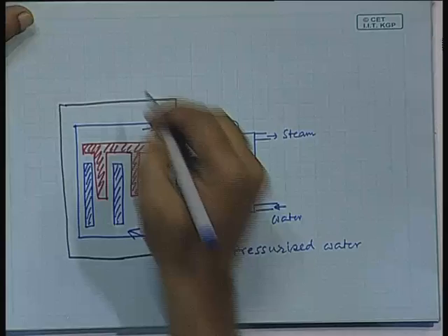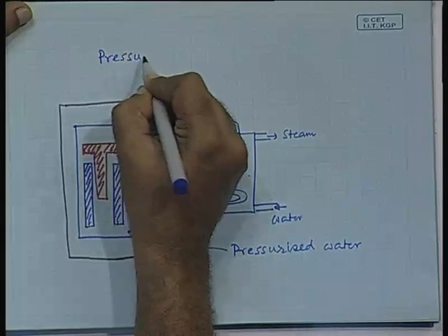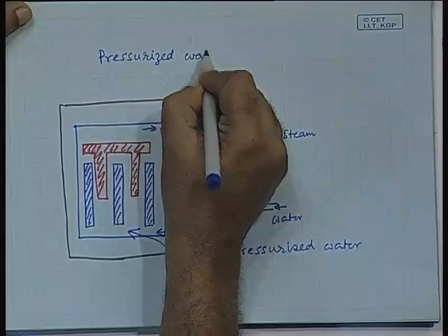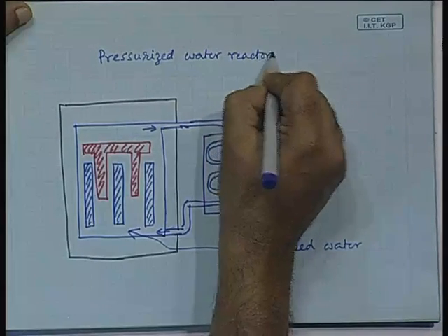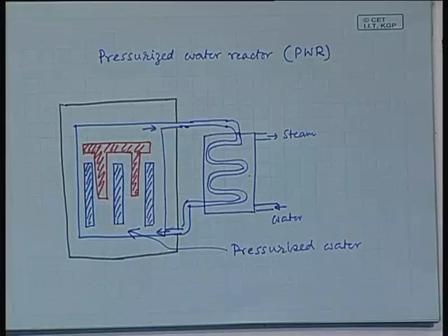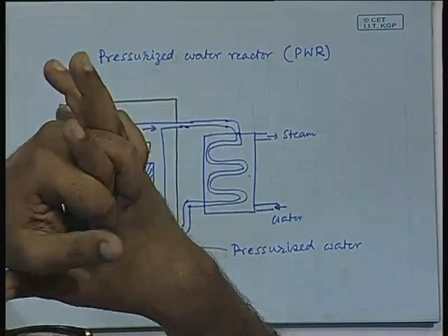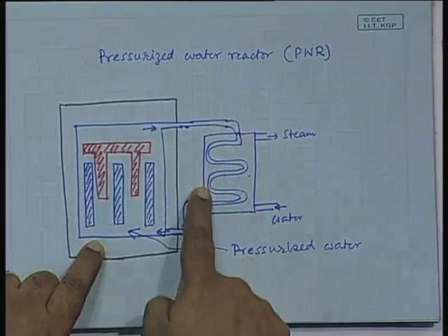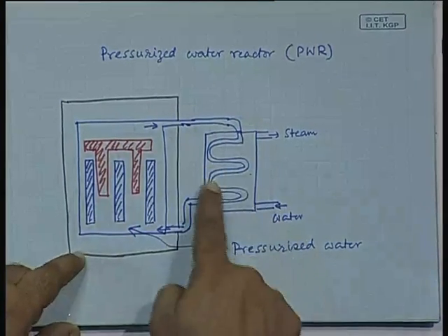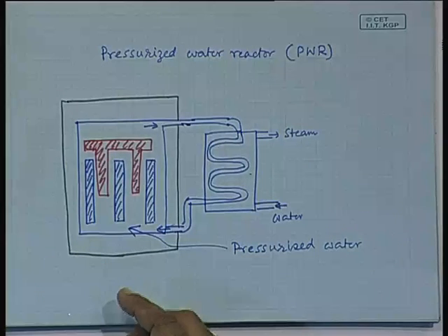So, this is called the pressurized water reactor, or PWR. So, here also the same substance, the normal H2O water, is being used both as the coolant and as the moderator. Now, in the next stage we can think of improving the moderator to D2O, the heavy water, in which case it is the same cycle, but it is pressurized heavy water that circulates through, in which case the moderation will be better.